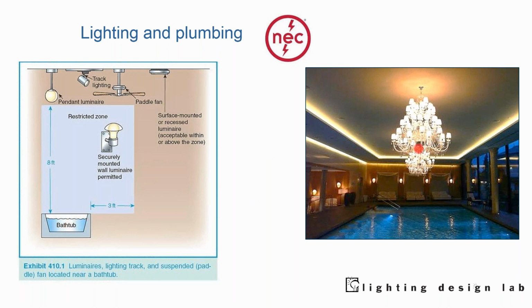So for instance, this chandelier, I'm sure this is actually taken from my second home. Here we have water. As long as it's 8 feet above the water line, or the high water line, you're okay. And as long as these sconces can't be reached while you're standing in the water, you're good to go. So these codes impact water and storage.